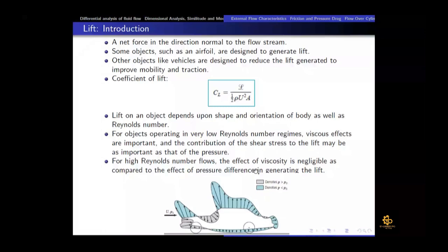Here the flow is coming. This is the flow over a car. You can see that we have stagnation pressure in front, then positive pressure on the windshield, but we would have negative pressure, low pressure, on the upper side, and on the bottom surface as well. So we try to make it such that it doesn't have positive lift, otherwise the traction of that vehicle would be less. We want to make it more ground bound rather than air bound, because we want some kind of control of that car, right? So that is the pressure.